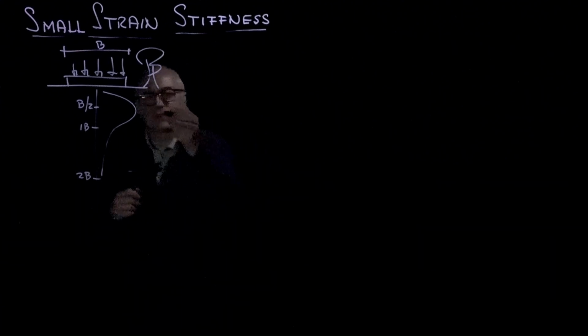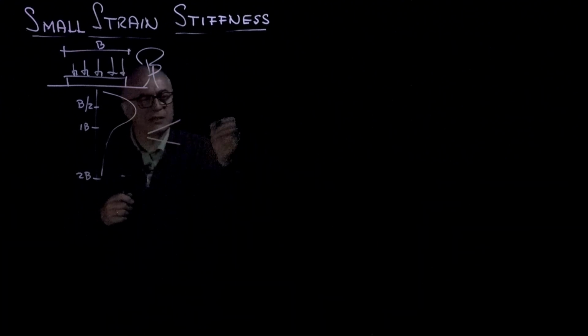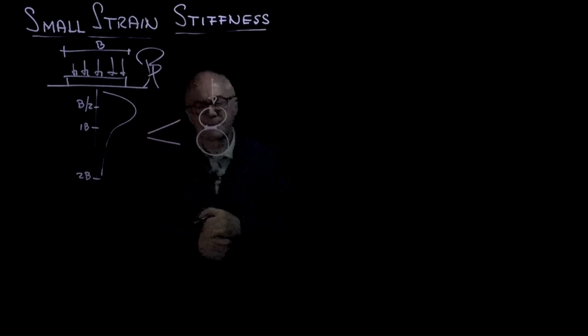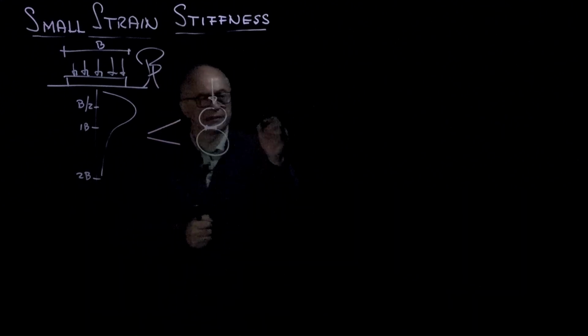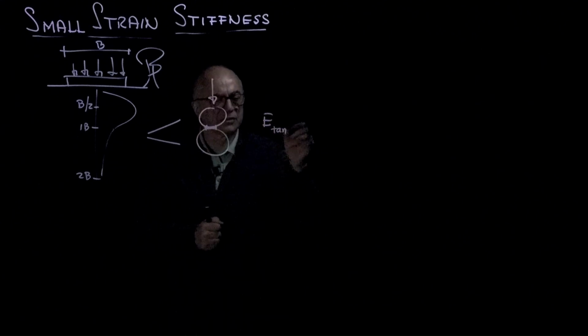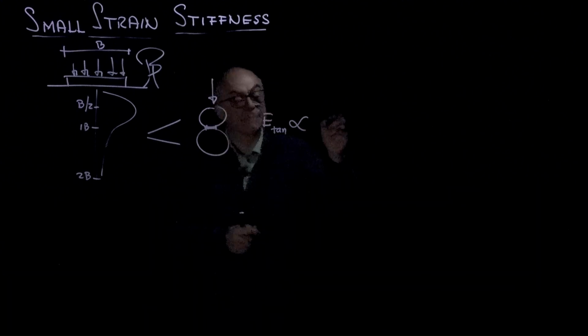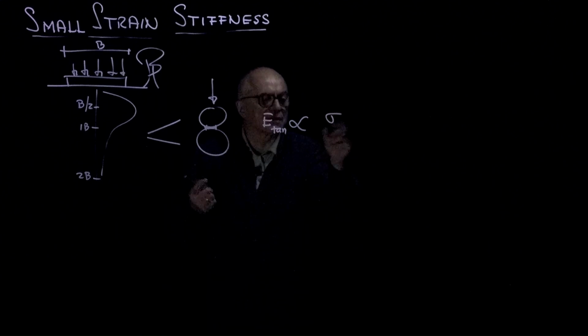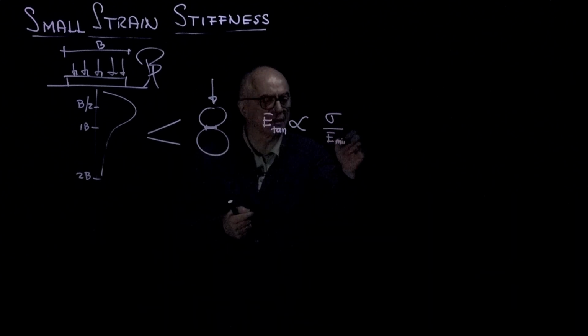And so if we zoom in, we see particles subjected to normal load experiencing a contact flattening, and we anticipated that the tangent modulus of that deformation is going to be proportional to the applied stress normalized by the modulus of the mineral that makes the particles, to a power of 1/3.